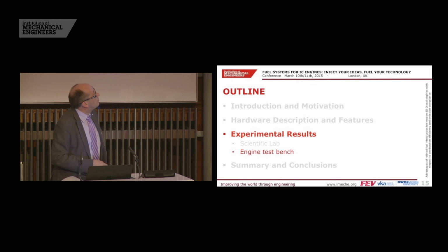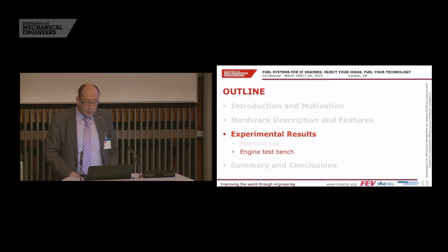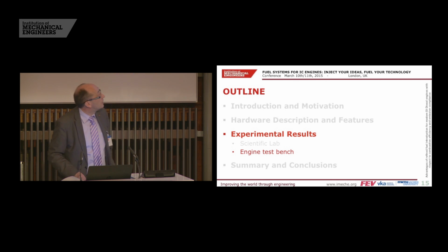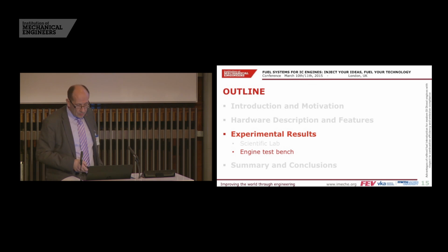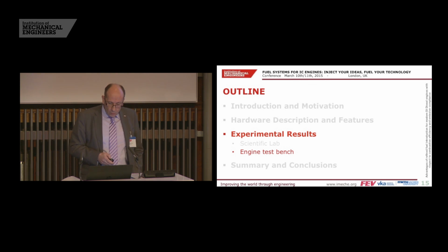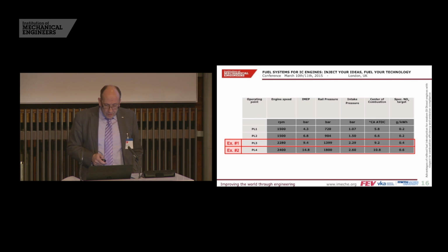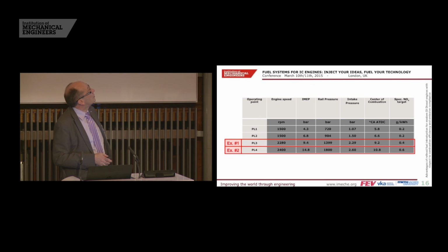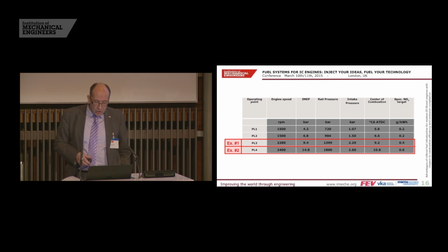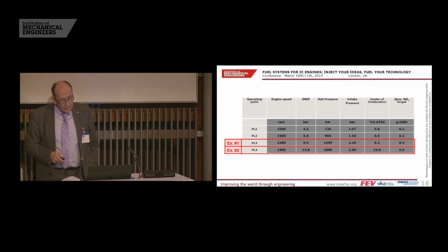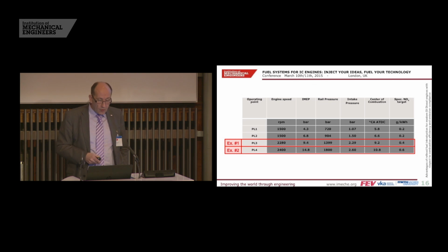Then, of course, with that very positive and very promising results coming from this high pressure chamber, we moved to our single cylinder engine in order to do investigations in a thermodynamic way. I have here the summary of the investigated load points. So in total we concentrated on 4 major load points in the part load area, which are representative for NEDC.